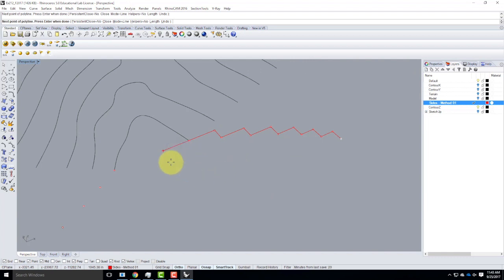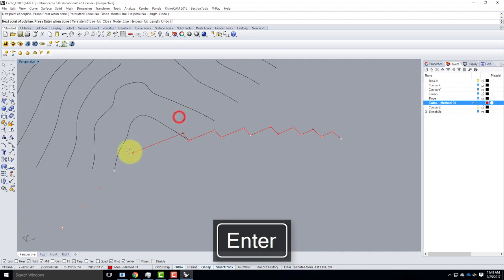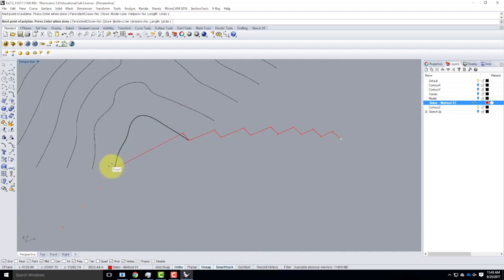OK, so now wait a minute. I got to this point here, and this next point is straight across. Well, I actually have to go down one more time and then over and back up because it's the bottom of a valley. So in this case, I need to know what my value was, which was 39.063 feet. There it is going down. We'll go straight across until we match up with this point there. Perpendicular, and then we'll start working my way back up this side.